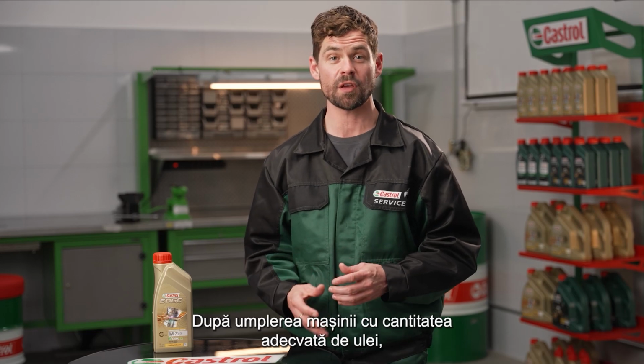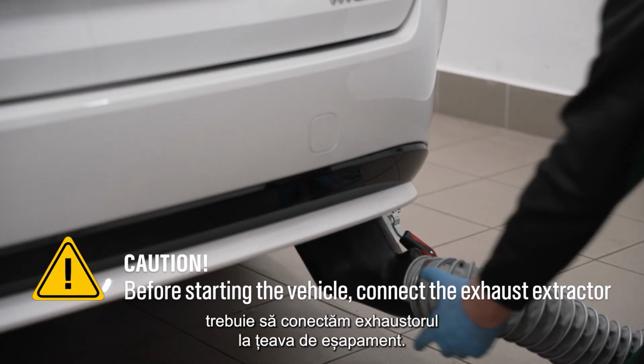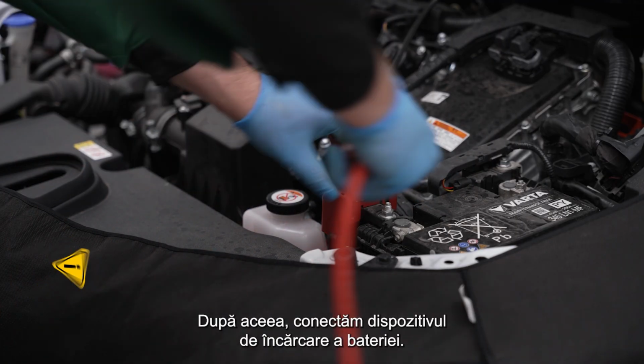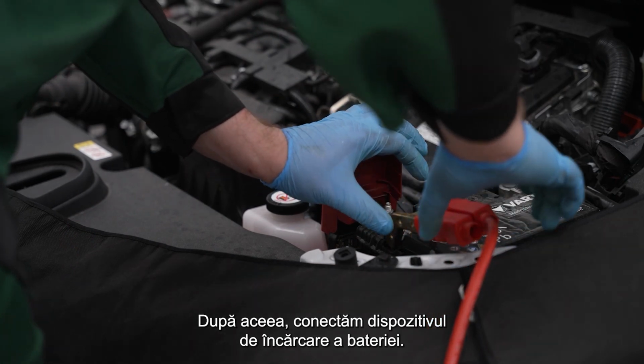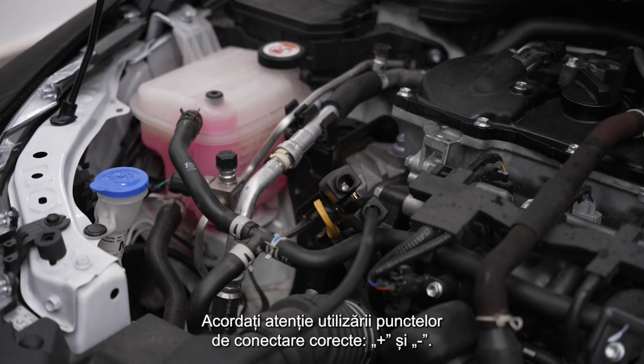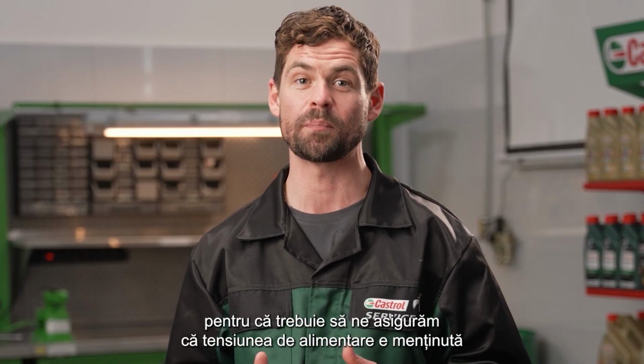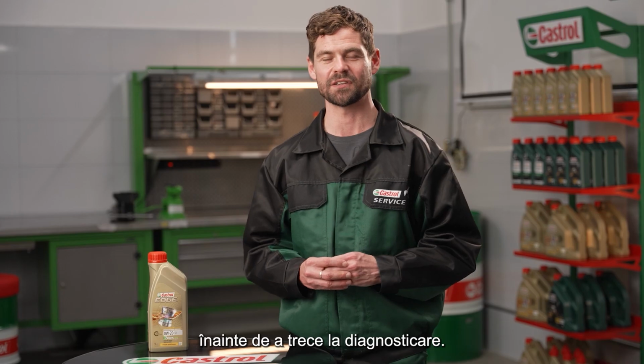After filling the car with the appropriate amount of engine oil, we have to connect the exhaust extractor to the exhaust tip. After that, we connect the battery charging device. Pay attention to using the right connection points, plus and minus. Connecting the battery is important because we have to make sure that the supply voltage is maintained before we can move on to the diagnostics.